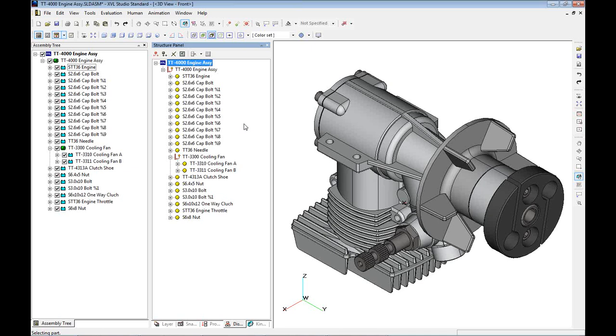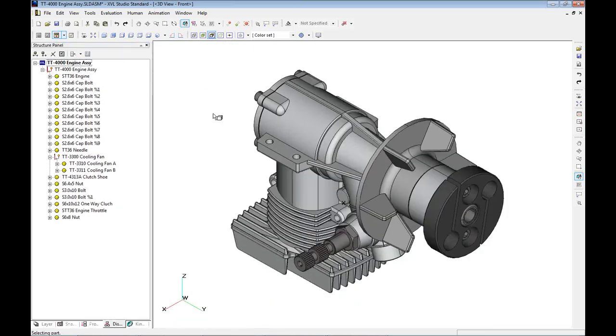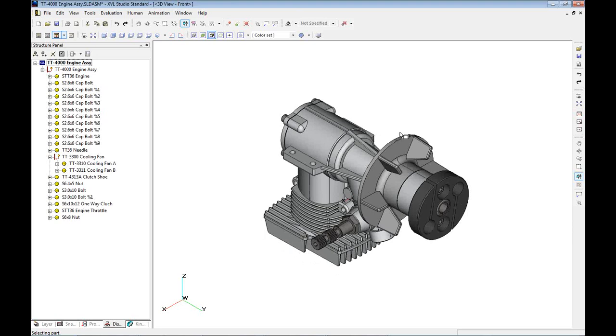You can include all of the parts in the model or some of the parts, and you can add additional attributes, such as part numbers that you may want to include in call-outs when we add them as we go through. So we've built the disassembly tree automatically by just including all the parts, and you can see it's indented to include sub-assemblies where necessary.